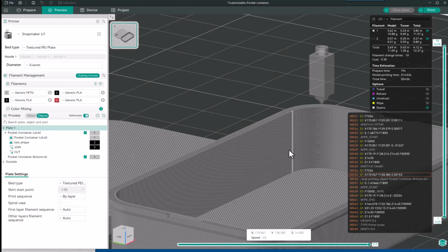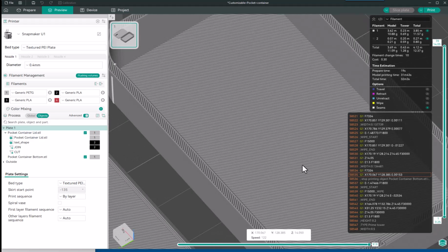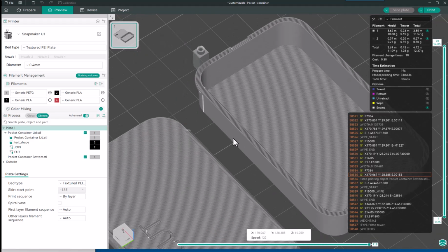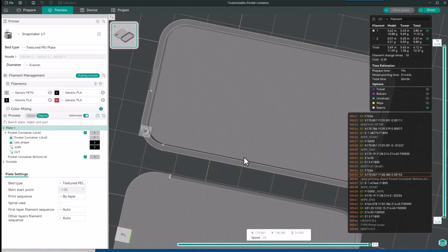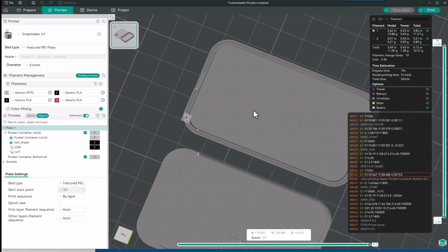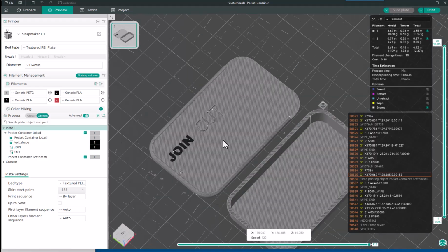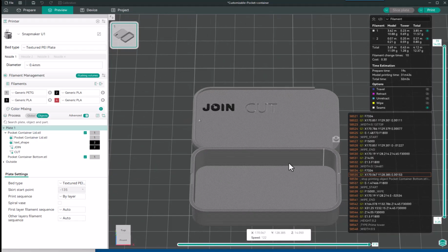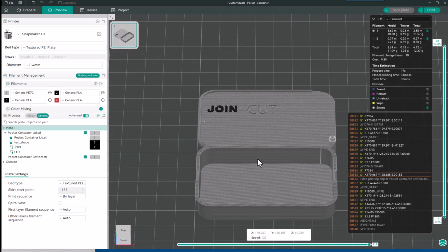And you're always going to have seams on the inside and the outside. See the same difference over here. And same on this print right here. Wherever it restarts and stops, you're going to see that seam, which you kind of don't notice. But that's what the white things are. Because I know people have been like, oh my goodness, I have white in here and I'm not even using white. Well, that's the reason. So you can't do anything about having seams, but you can move them around. But the program usually just puts them in a line, and that's usually the best way to have them.